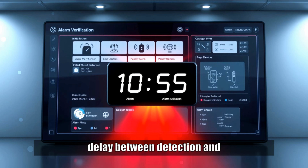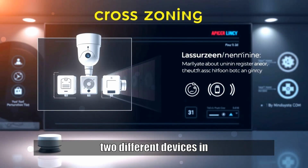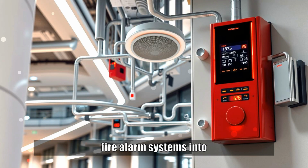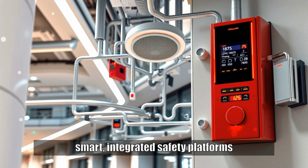Alarm verification involves a delay between detection and alarm activation, during which the system checks for confirmation from another device or waits a set time to ensure the threat is real. Cross-zoning requires inputs from two different devices in the same area before the alarm is triggered, minimizing the chance of false positives. Technological advancements have transformed fire alarm systems into smart, integrated safety platforms.